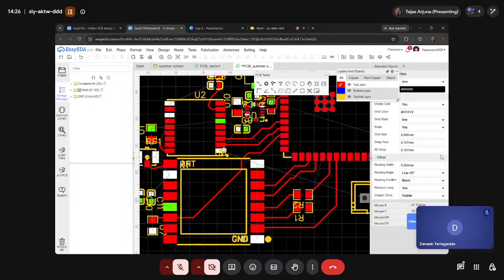And if there is any other part that is viable to get the radiated EMI, then it takes it as noise. So these antenna-like structures, the long traces and also the large loop areas, act as antennas for radiating EM waves and also for receiving them. So EMI is more prone because of those structures. We need to avoid them as much as possible.